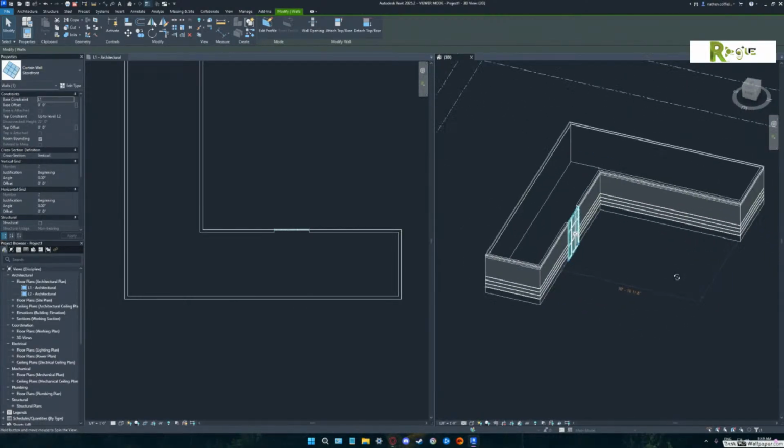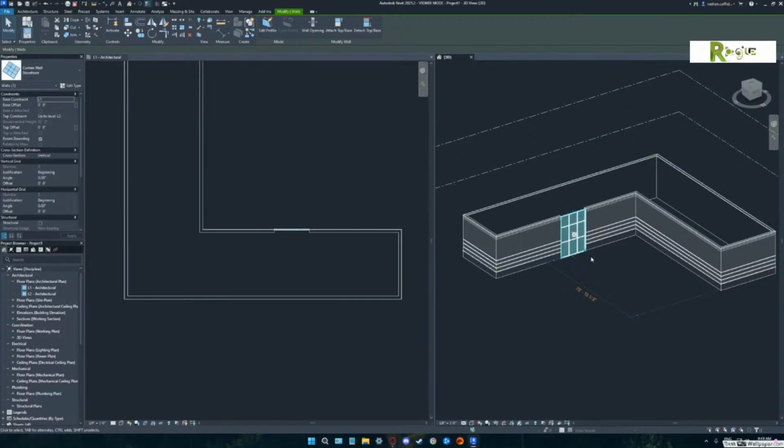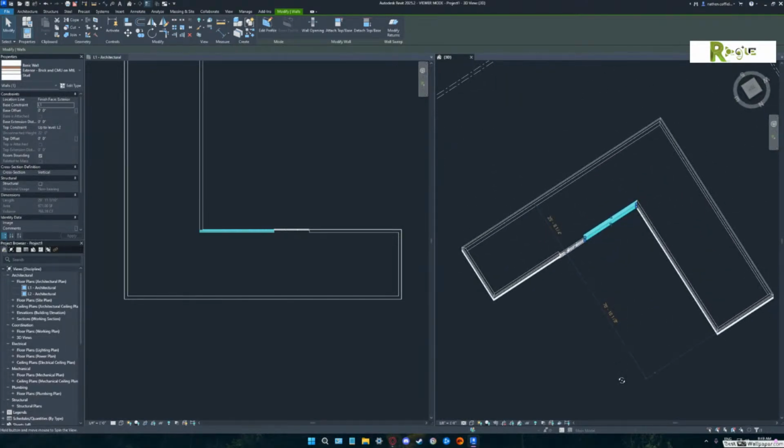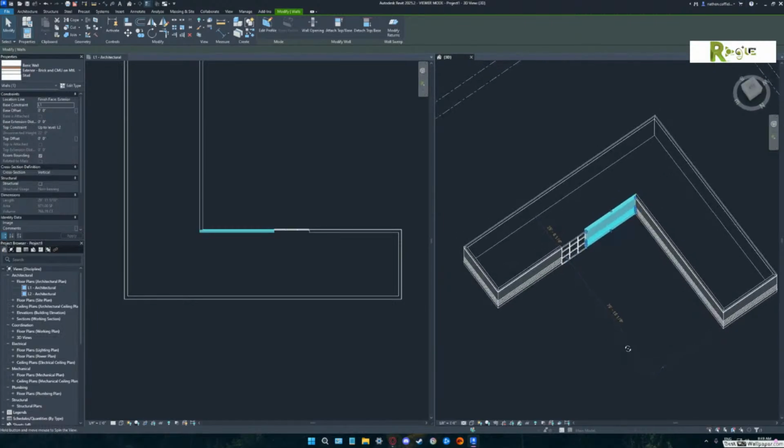Now, it might be a good idea to start slapping some dimensions, but you can see anytime you pick any object, dimensions show up automatically. Pick another object, pick another one. You see how that's 70 foot? If you said, no, I wanted that to be more like 60 feet, you would just click on the 70 foot and type in 60 feet.